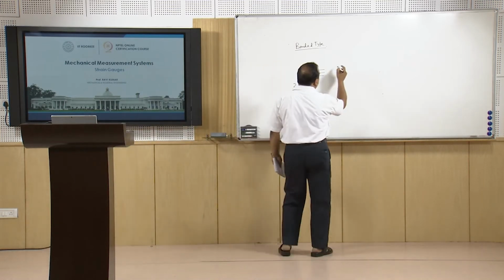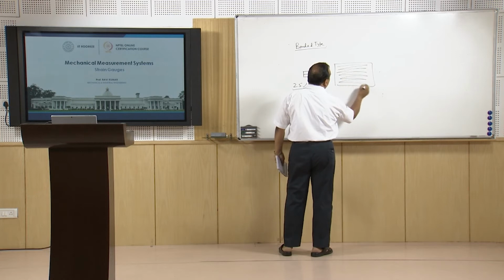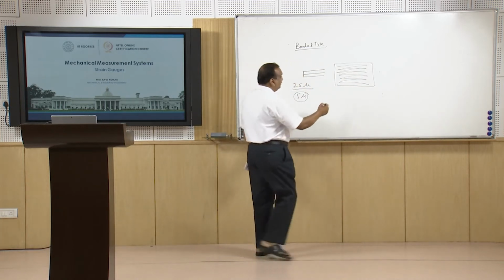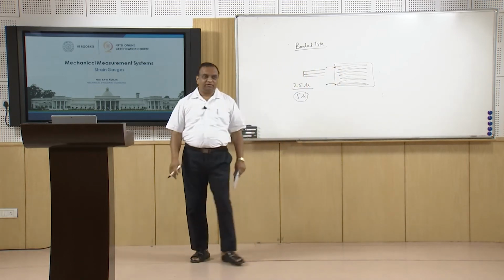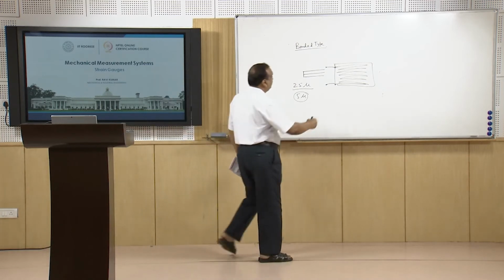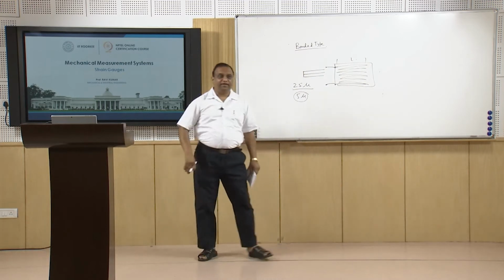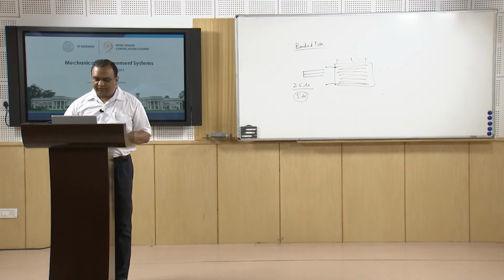There is a grid of wire. Not just a grid, they are serially connected grid of wire. It means the wires are like this, very thin wire laid on the substrate like this. Okay? So they offer very high resistance, and here suppose they are terminated, and this is the effective length of the strain gauge. So they offer a very high order of resistance to the current.